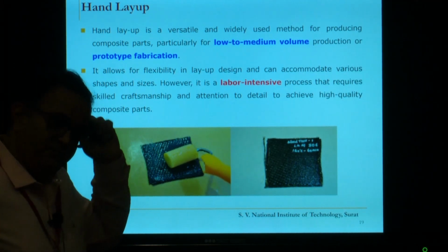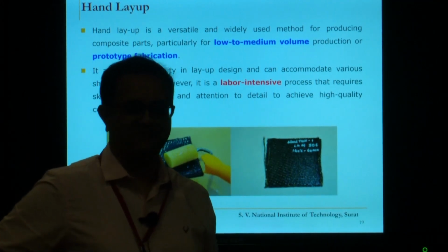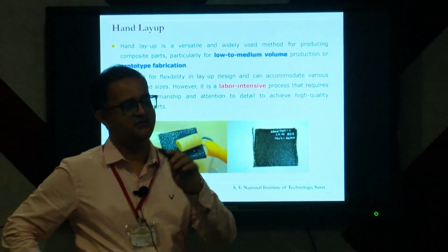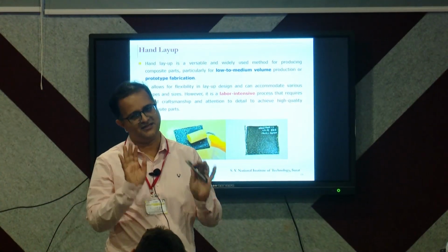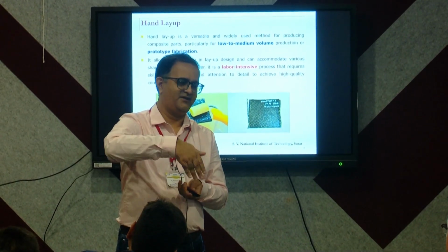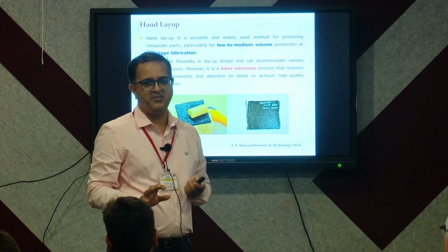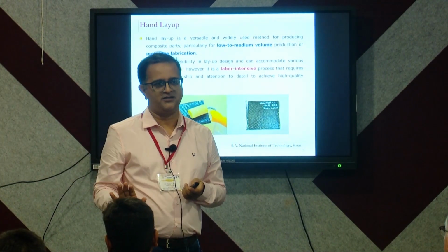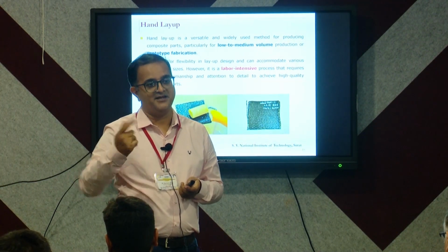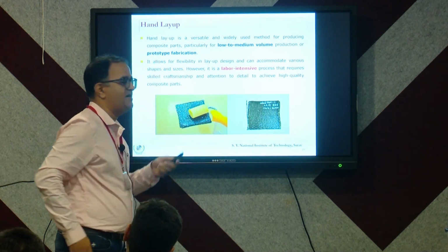But in a way, this gives you the best results because you are always sure that this is going to give you a result. You will not face situations like what Arjun faced, because the amount of resin that you are using is restricted. You cannot just put a bucket over there. When you use the brush, everything is limited. So, here getting a part is a sure thing. Quality or strength getting compromised is a different thing. So, you need to keep on repeating this, and that is why this is called a labor intensive process.